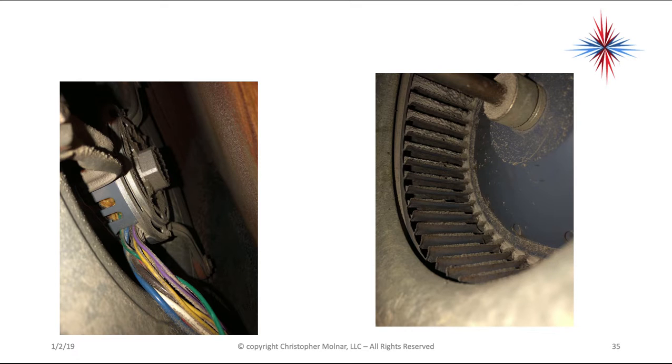Taking a look at the blower motor and the blower wheel, you can actually, on the picture of this blower wheel, see the cupping, okay, and see that all of this dirt and dust and debris is built up on those cups. This blower is not moving a ton of air.